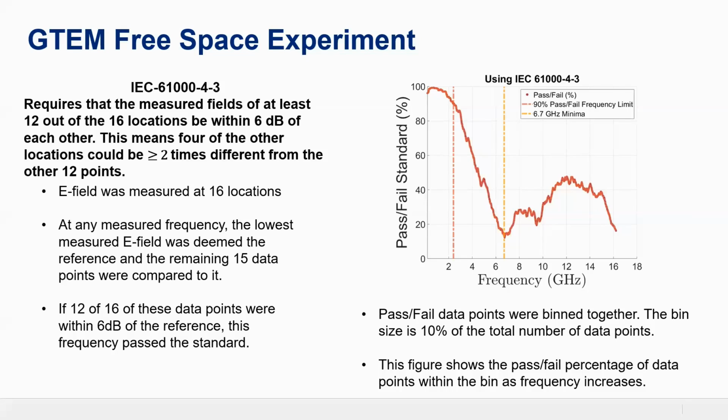So say if you're trying to qualify parts for, say, FCC or basically telecommunications, or also calibrating your sensors, you can rest assured most likely you're going to have a lot of frequency points that you can use there. Now, what I want to point to your attention, though, is the global minima. So at this point, this is 6.7 gigahertz.